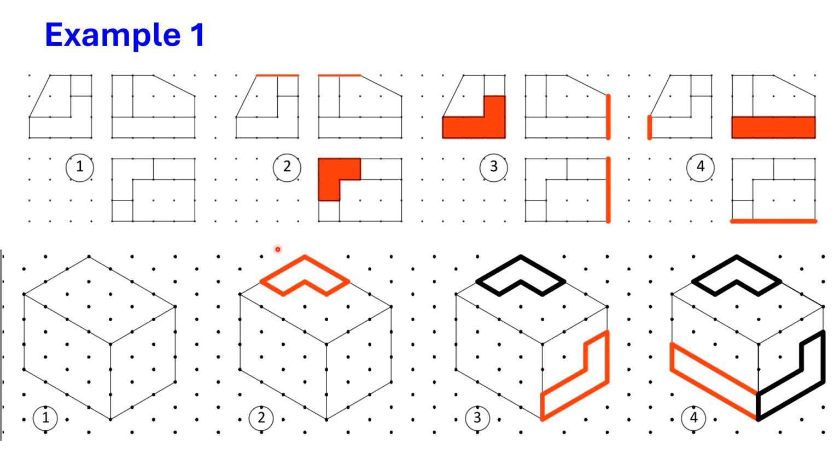So if you see here, this is the front view, top view and side view, and you draw a front view window by taking the dimensions. If you identify the grids, these grids are horizontal and vertical in the orthographic views. In isometric drawing, the grids are oriented with equal angle. So if you assume this is the x-axis, y-axis and z-axis, the angle between these three axes is equal.